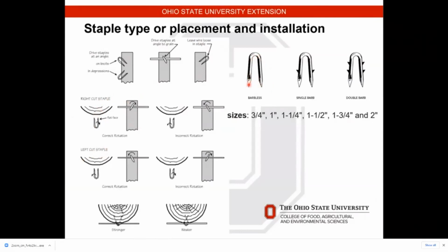Okay. The right-handed staple, you want to tilt it to about 2 o'clock or a 30 or 45-degree angle and drive that staple in. What that does is, when you drive that staple in, these barbs go away from each other, giving you a much stronger anchor than if you put it in backwards. They would cross over. And if you put the wire on the wrong side of the fence, they're going to push them right out. Okay.